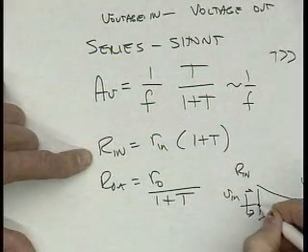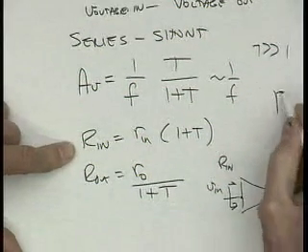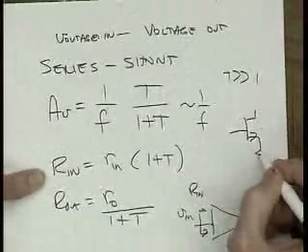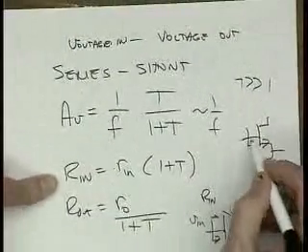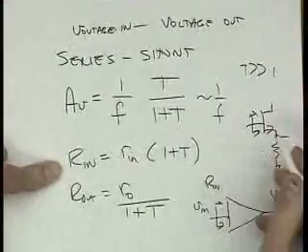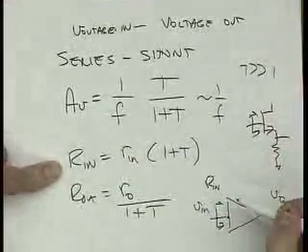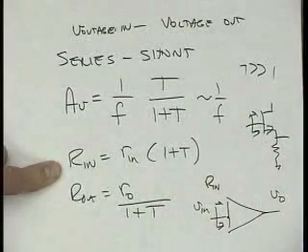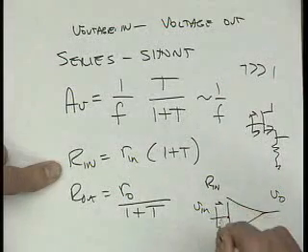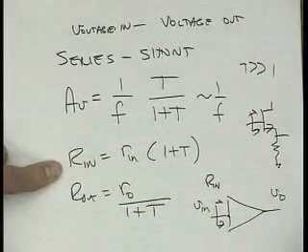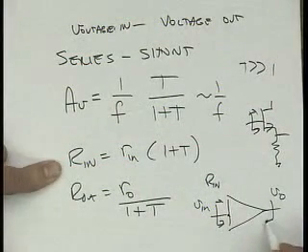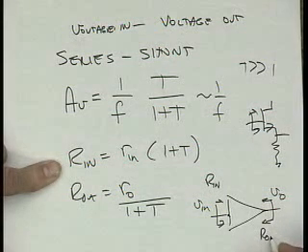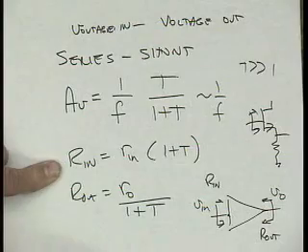It's like a source follower, which has a really high input resistance. For MOS, a lot of our amplifiers have very high input resistance because we go into a gate. But a common gate amplifier doesn't, so it's not a good voltage amplifier. What do we like ideally for a voltage amplifier output? Really low output resistance. We'd like it to be a perfect voltage source.